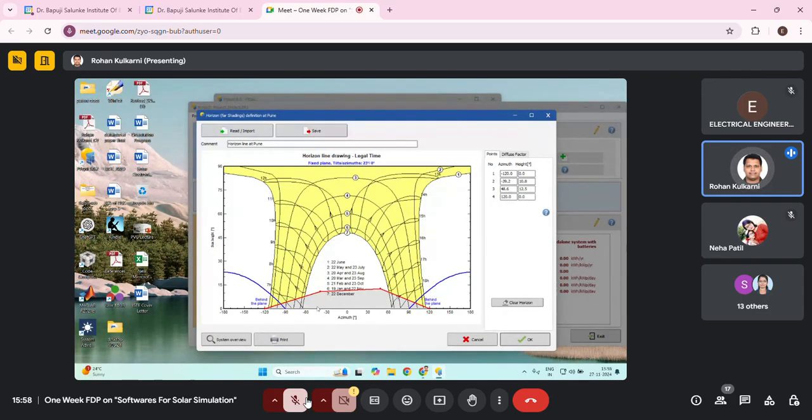You can see the sun height on the x-axis. So we can define, okay, there is an object. Now you can see that object can create some problems at the end. At 6 o'clock or 7 o'clock it can produce some shadow on your panels, or like that. So this is also called far side shading.